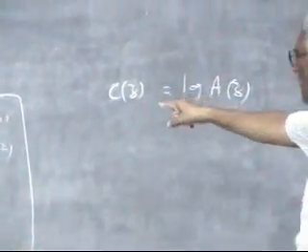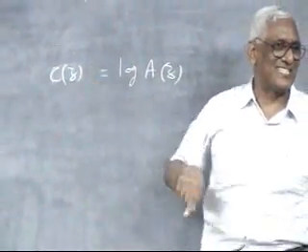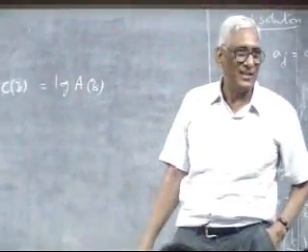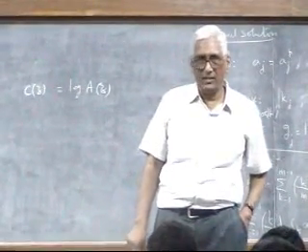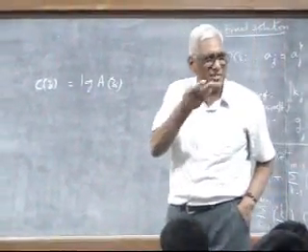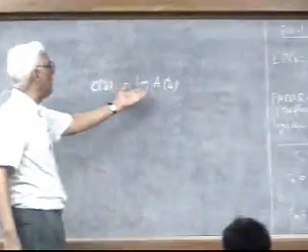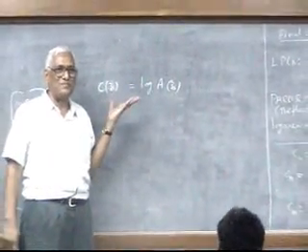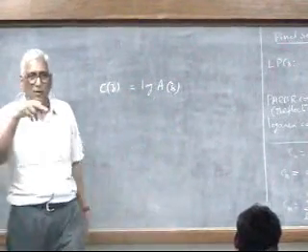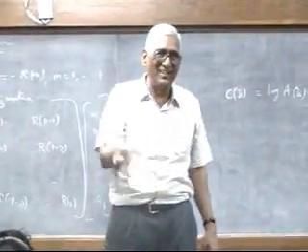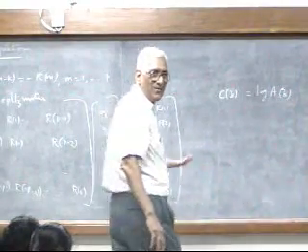So what you are basically finding is the coefficients of the inverse DFT of this in some sense. You get the point I am saying? You got that? So hence it is called that, and once that hint is there, everything is obvious. Because after all, how does it matter if not Az, if it is minus Az, what happens? It is all the same. Minus Az is nothing but my all-pole filter.